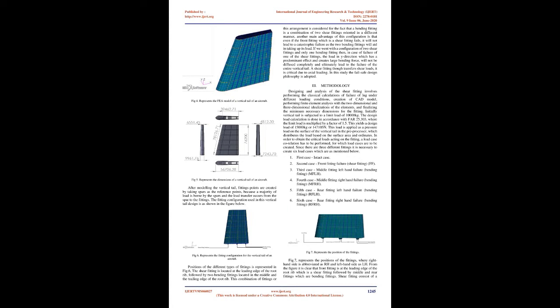Simplified analysis method. This method involves assuming the nature of failure and calculating the FOS, factor of safety. This method seems to be easy, but it doesn't give an exact result. Air Force method. This method considers most of the failure modes as mentioned above, and uses empirical curves to determine more accurate allowable loads. This method allows for lugs under axial loading, transverse loading, and oblique loading. This method also accounts for the interaction between the lug and the pin.